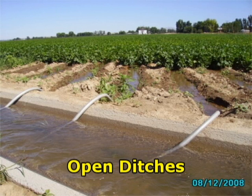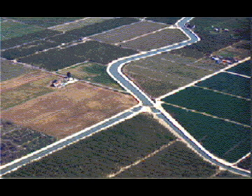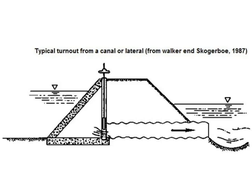Open ditches. A ditch that will safely convey the required stream should be selected. In designing a permanent ditch, a profile of the center line showing the location and elevation of the water supply and any required turnouts, crossings, drainage bypasses, and the like is required. The water level at field turnout points must be high enough to provide the required flow onto the field surface.